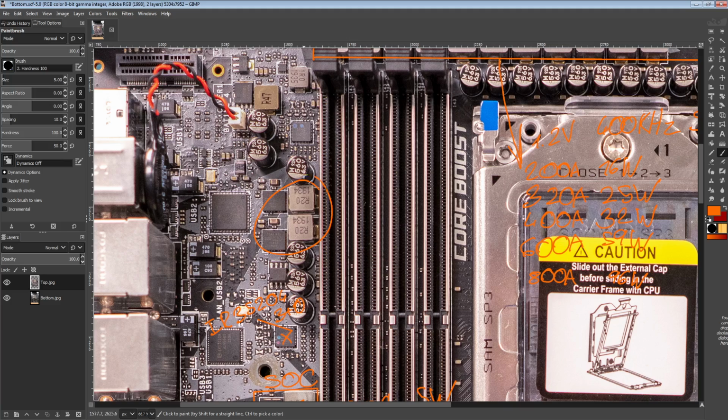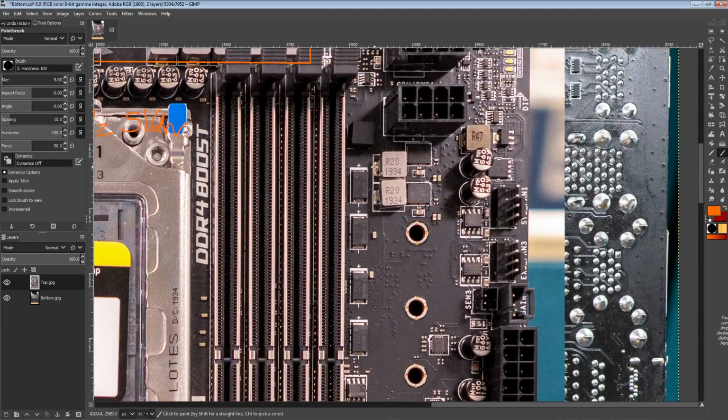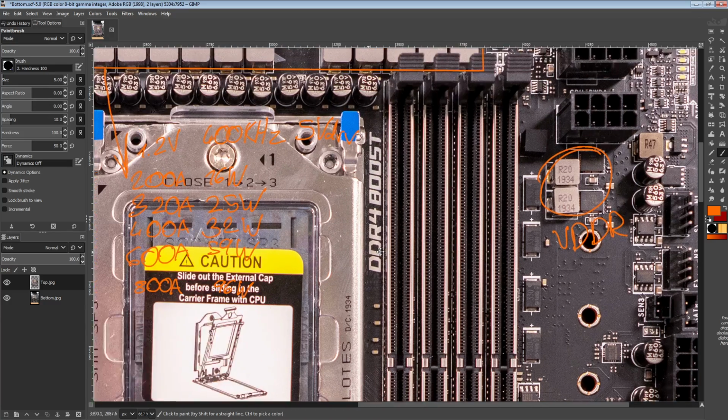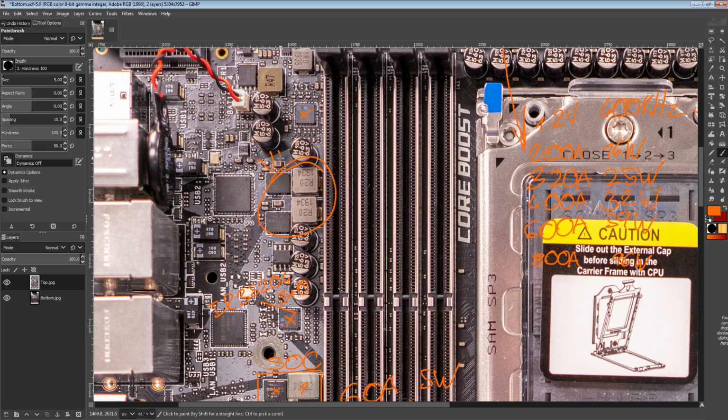Now, the memory power delivery is where MSI is just super overkill. Insanely, ridiculously overkill. And of all the VRMs going mega overkill, memory power delivery is the least important, I'd say, because here's the thing: if you actually care about memory overclocking, you're probably going to want to pick up a mini ITX motherboard or some other motherboard with only 2 DIMM slots, and those tend to be kind of cramped for space and don't really go ridiculous on the power delivery.